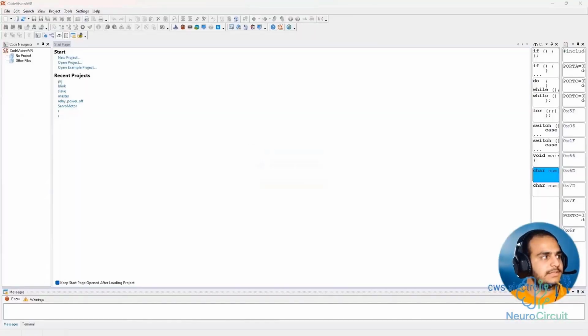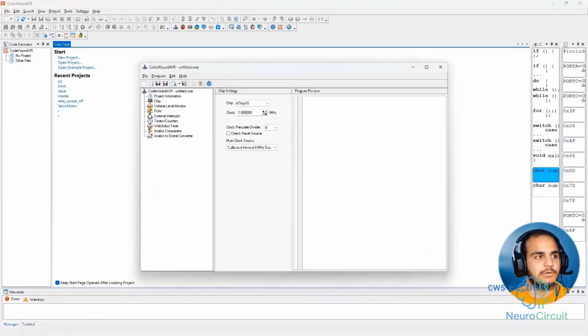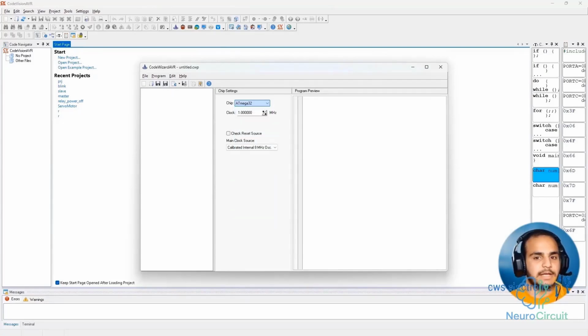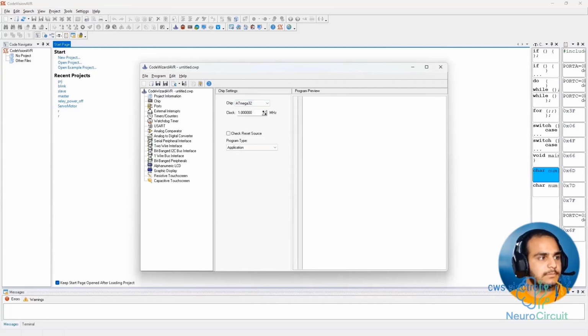In CodeVision, I'll start the project from scratch again, creating it. By now, this process should really be ingrained for you, and you should be able to create a project with your eyes closed. In the microcontroller selection section, we have the ATmega32 again. Let's move on to our port section. For the LCD, we don't need to do anything extra. Now, as you'll see, we just want to set up our buttons and LEDs.